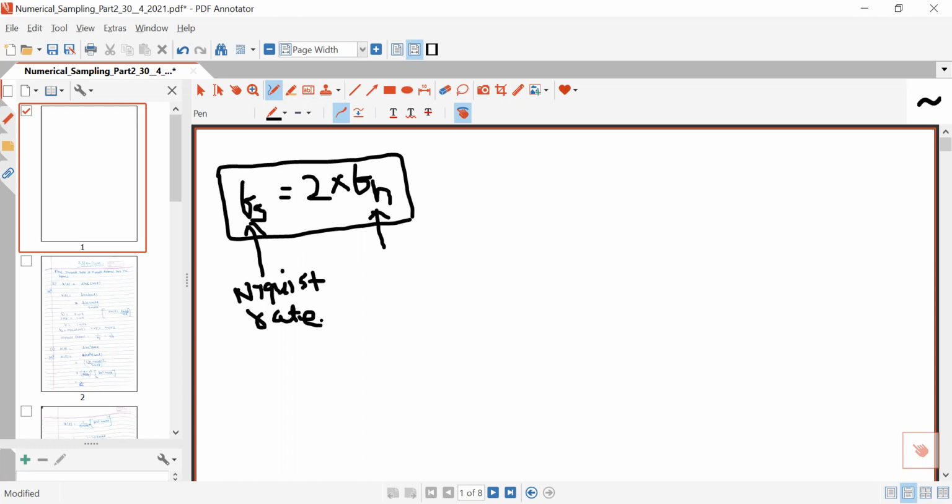And here the minimum sampling frequency, written with the term fs, is called the Nyquist rate, and the reciprocal of this Nyquist rate will be the Nyquist interval. So basically, in problems related to the sampling theorem, you have to calculate the Nyquist rate or Nyquist interval. But you must remember, the minimum sampling frequency should be equal to twice fh. If the sampling frequency is less than twice fh, then you will get a phenomenon termed aliasing, and aliasing has severe consequences.